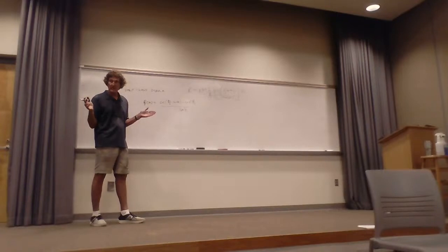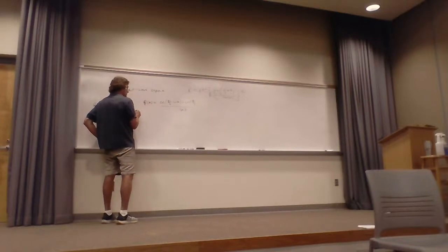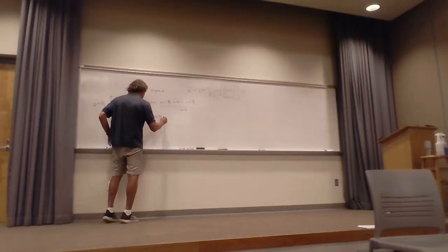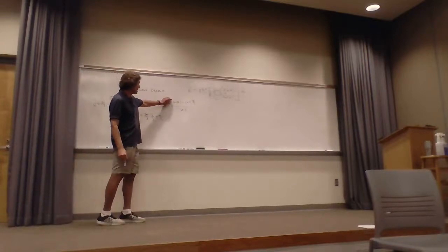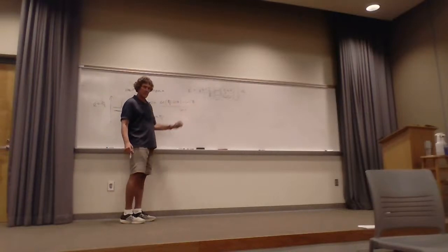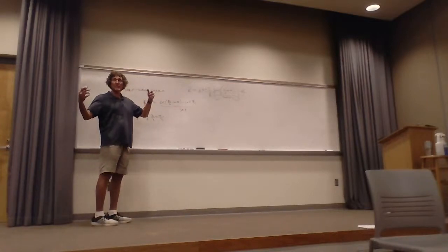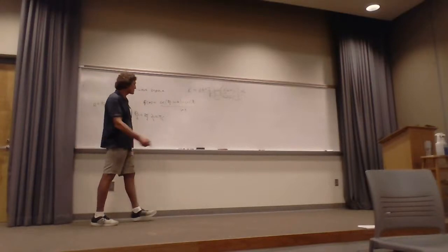The arbitrarily long dipole. Well, here, think about this. I said it's a half wavelength long, so beta L over 2, beta is 2 pi divided by lambda, times L is lambda over 2, so that's pi over 2. Do y'all agree with that? So if you take pi over 2 and put it in here, you have pi over 2 cosine of theta. But then when you put pi over 2 here, where beta L over 2, what happens? It becomes cosine of pi over 2, or cosine of 90 degrees, which is 0. Y'all with me? So this part goes away.